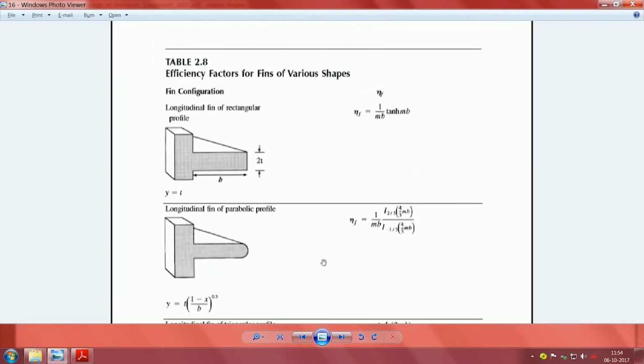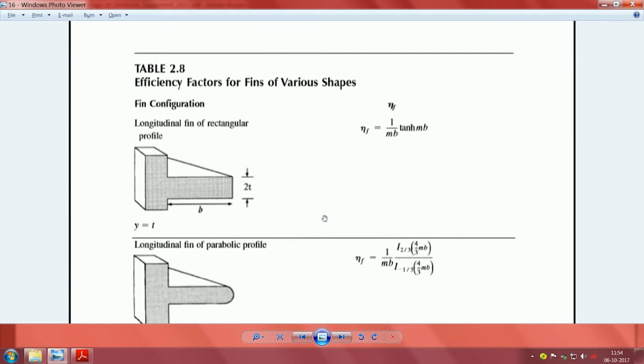Now, we come to a very interesting thing which I have told you earlier about: why we end up with fins of various geometries. As you come to the tip of the fin, convection takes away the heat. So, they are generally tapered, because in the beginning you need more conduction, and as you go further and further, the temperature drop is not affected very much by having an unwanted thing, because there is not enough area like that. So, the area gets tapered and tapered.